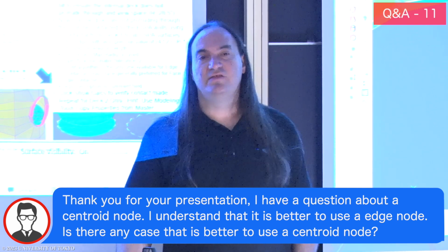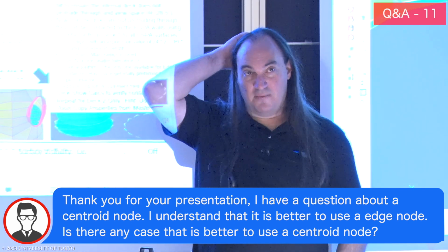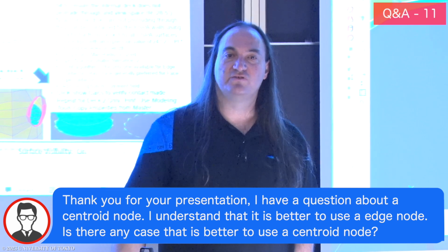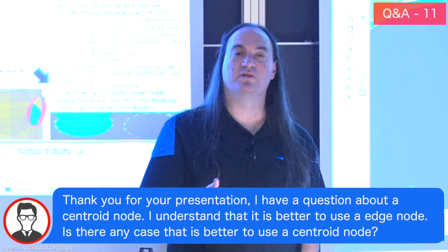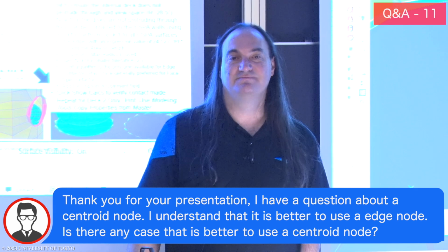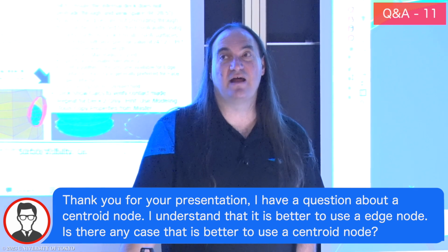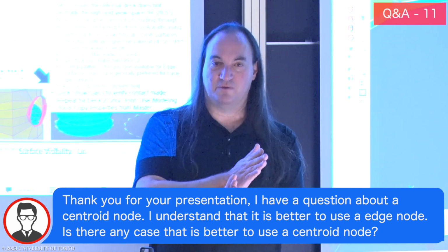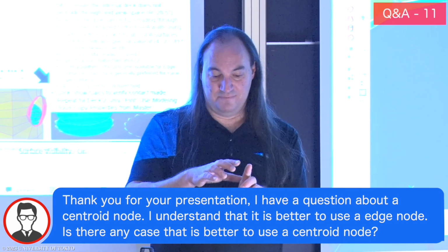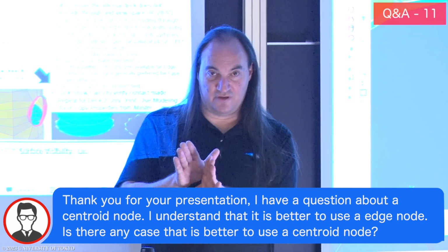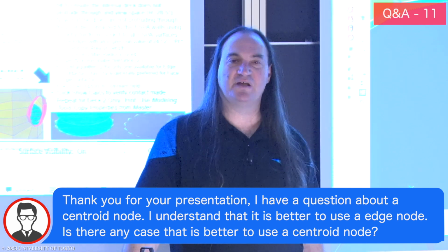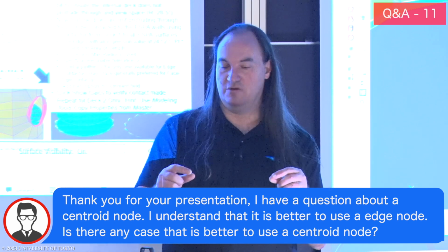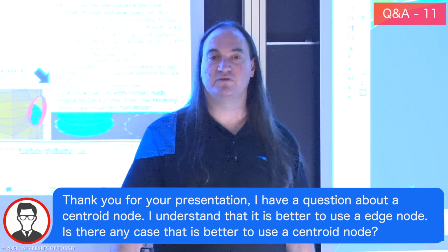So the other challenge with centroids is, again, at interfaces between surfaces, you have to manually find a way to make the connection. That's where I think the edge nodes have a strength, when I can merge nodes between two contiguous parts, or the same part, just different areas of the geometry of it. It just becomes easier to not have to figure out how to connect node 1 to node 2, because the software is programmed to do it.